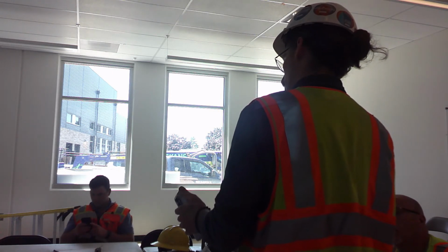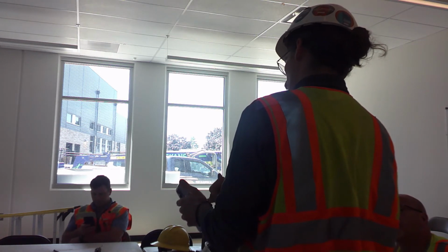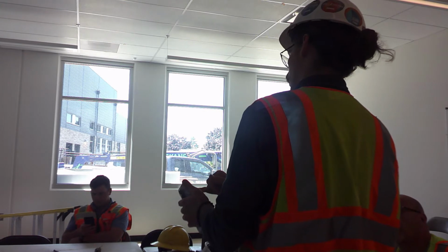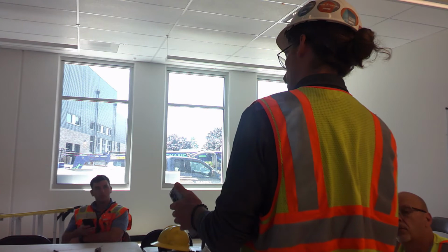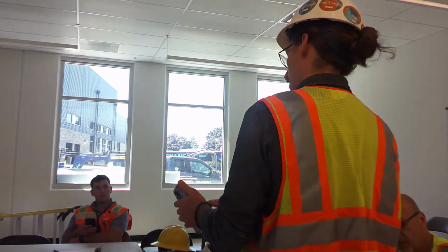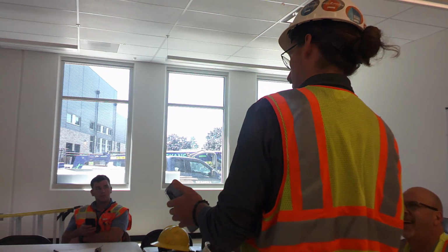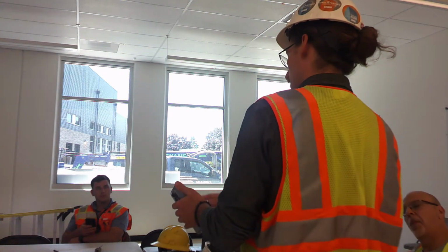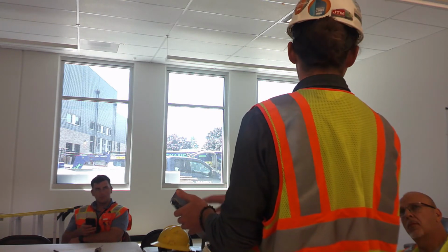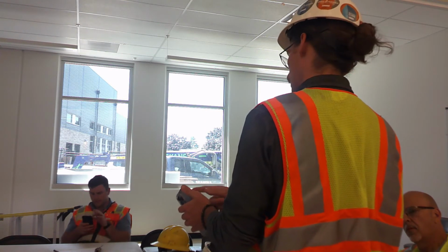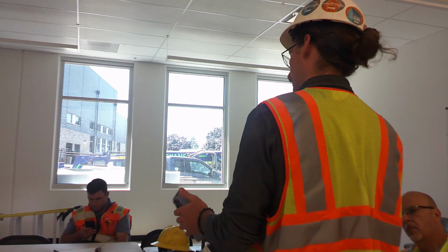So I'll go into this room controllers page. This will show all the controllers that are in the room. A little more info, the MAC address, the firmware version that it's on. If you actually go into the individual controller, it will give you an override for the lights, so I can turn that on and off, dim it up and down. So this is just to kind of see what the controller is doing. It's not the settings for the relays and dimmers. That's going to be in your relays and dimmers section.